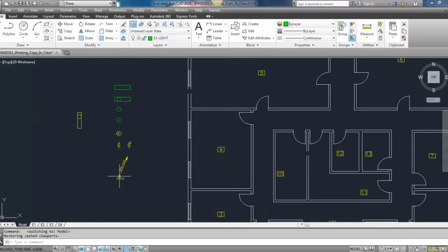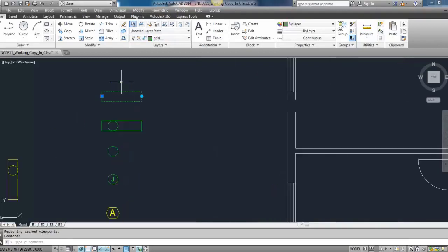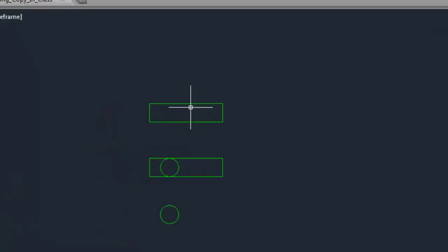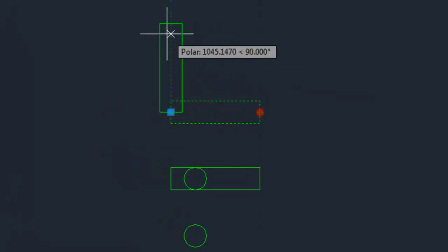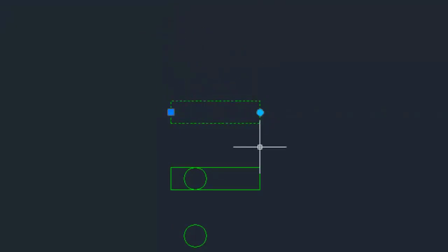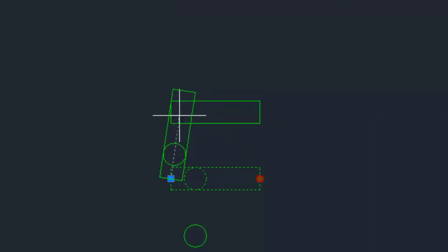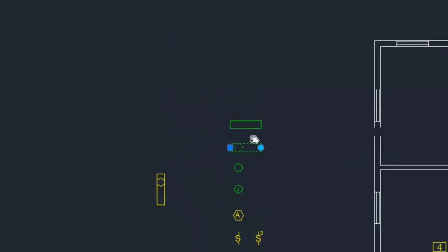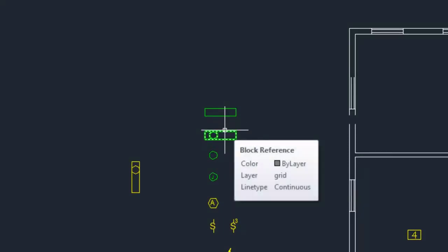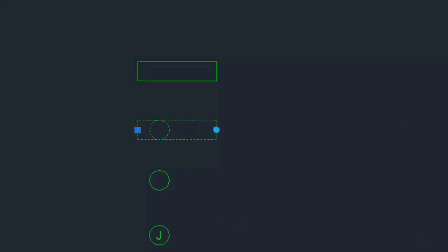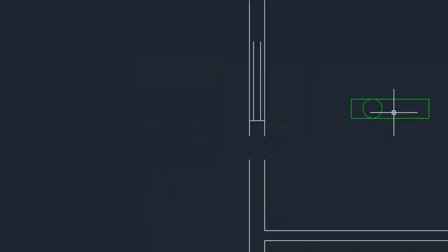I've set up a bunch of the blocks that we're going to actually be using in the layout. I've put them to the side just to make it easier for me to copy and paste them into their proper locations. Now I've done something else with these blocks, and I've really created dynamic blocks here. What that means is I've created these blocks with the ability to modify them quite easily and quite quickly. For example, the rotation modification makes it a lot easier. If I don't need separate blocks in multiple different directions to get this to work, I can just grab this block, and if I need a different orientation, all I have to do is click on it and rotate it into the orientation that I need.